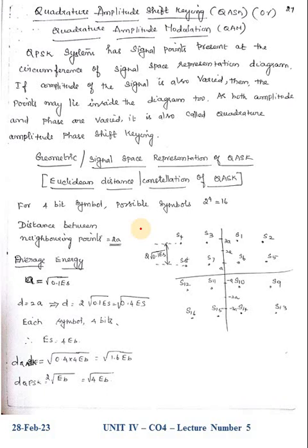In the previous class we discussed QPSK, BFSK, BPSK. The difference between QPSK and quadrature amplitude shift keying is that here the amplitude as well as the phase are modified with respect to the input symbols. That is, in phase shift keying, the phase of the carrier is modulated, whereas amplitude is kept constant. In FSK, the frequency of the carrier is modified while maintaining the amplitude levels constant.